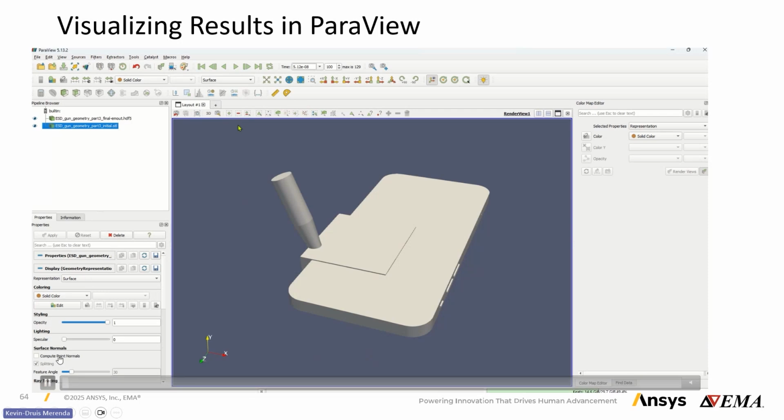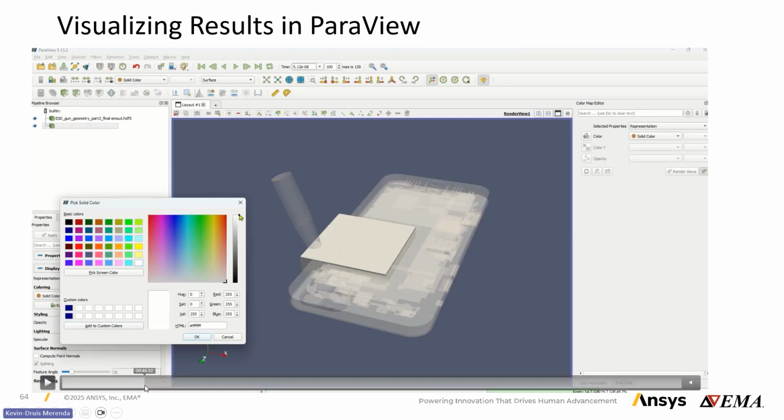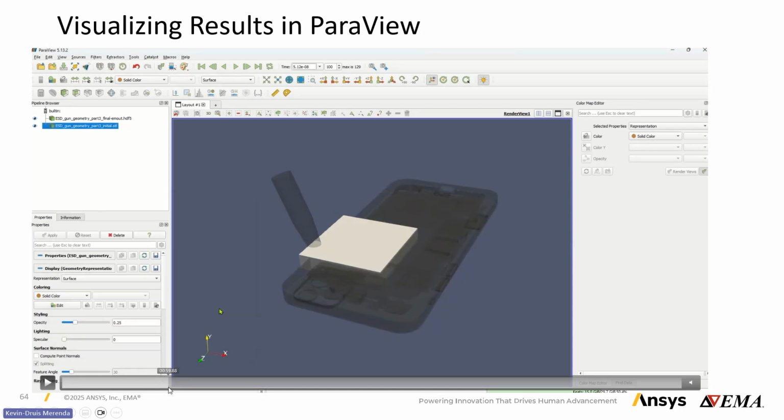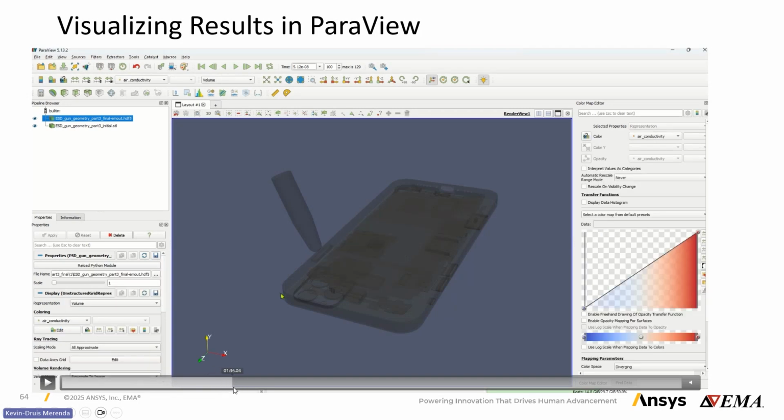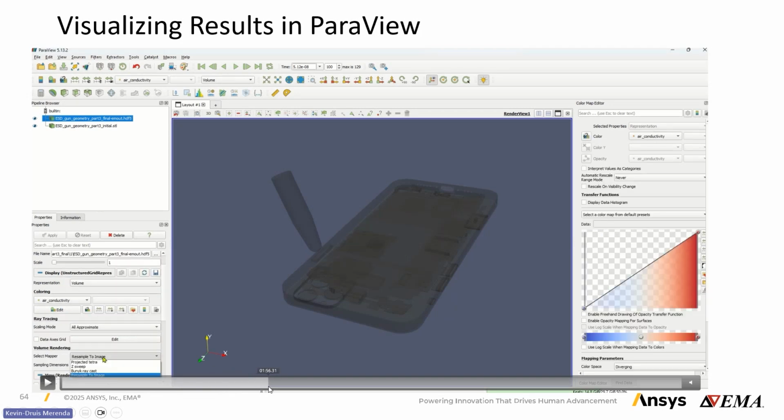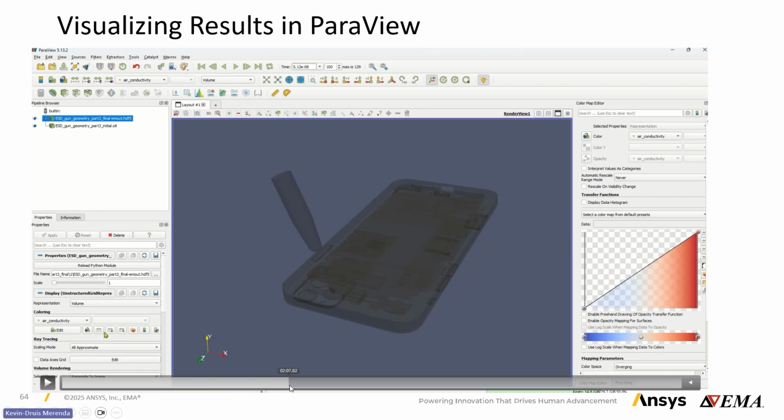In ParaView, we have a lot of things that we can do. They're called filters. You can right click on any of these data sets and do various processes with them. You can integrate the variables. You can create time annotations. You can also extract data in various places. In our case, we're going to change here the opacity of the geometry so that we can keep the geometry in the background and highlight the location of where the air became conductive and where the discharge occurred. So here we're changing some of the settings of the actual results file.